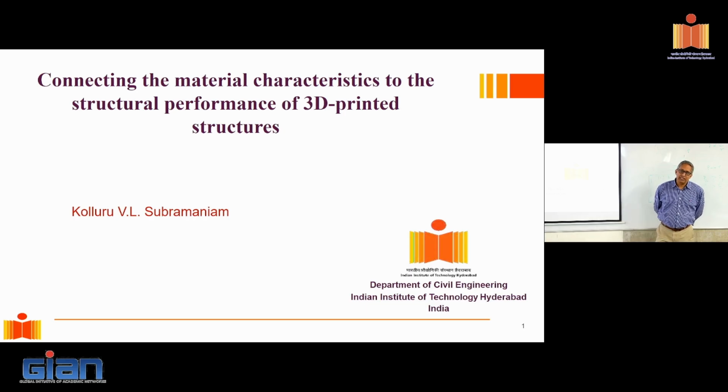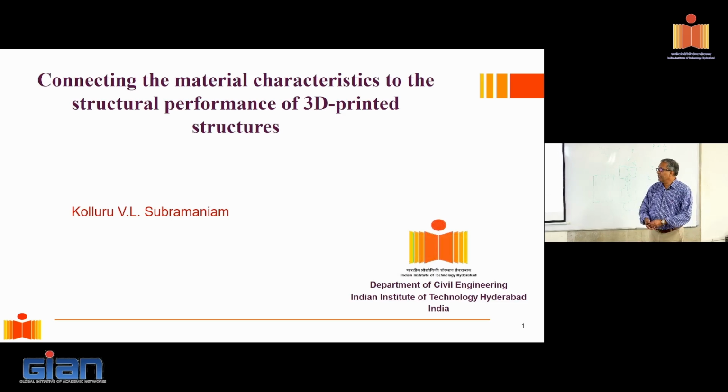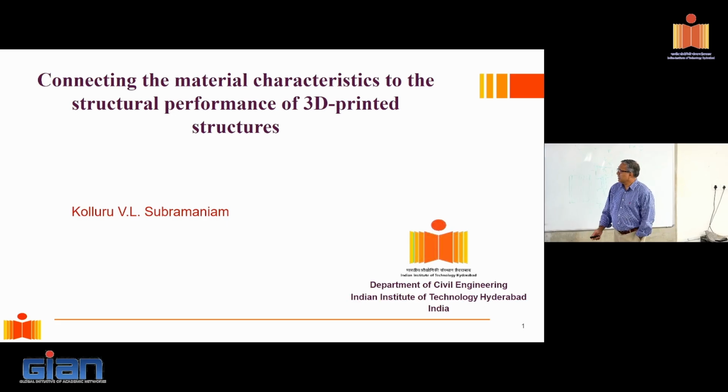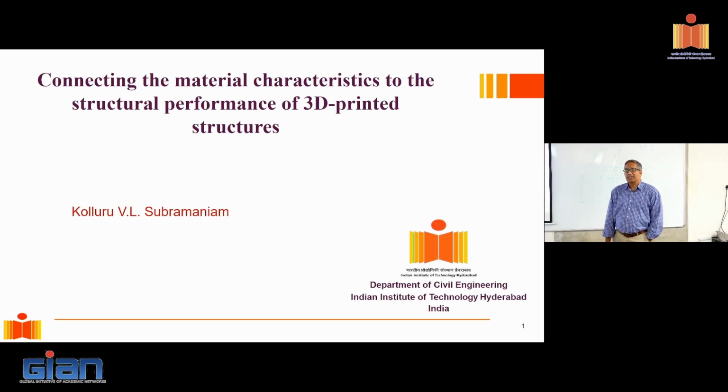Now extend that to the case of printed concrete with its own requirements, which are pumping, then it is extruded, so extrusion, and then shape retention followed by buildability. And all of these are related to definite thixotropic properties of the fluid phase, ultimately of the suspension, right? So what I want to do here is now get into the hardened properties. So what we are looking at is connecting the material properties with the structural performance of a 3D printed structure.